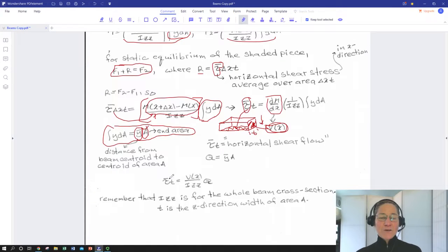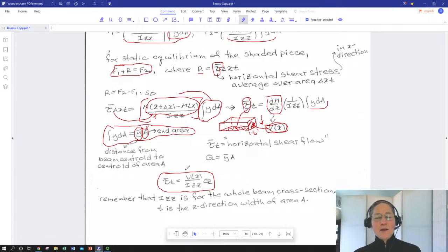What we've now defined here, basically by equating this tau, evaluating this expression, substituting in big V, the shear force on the cross section, for dM/dx, and then substituting in y bar A, times the area of that shaded slice, we have a bona fide algebraic expression for average shear stress and beam dimensions, applied shear force on the cut face, so basically the x